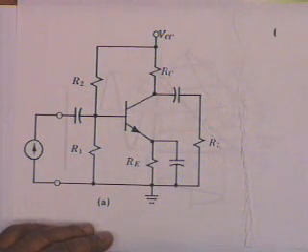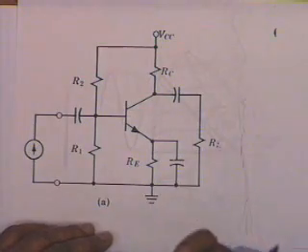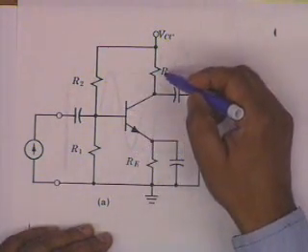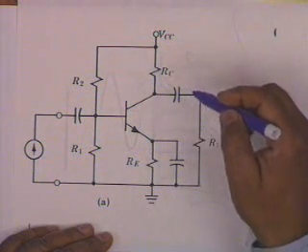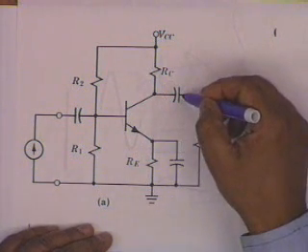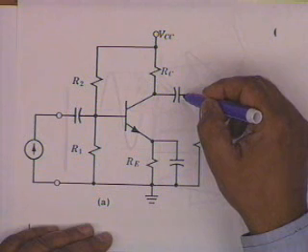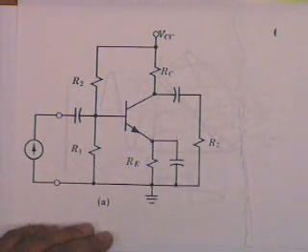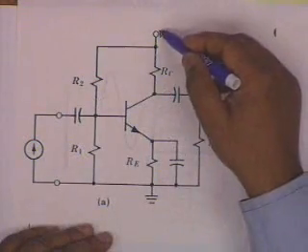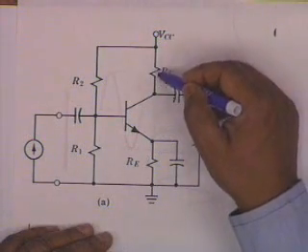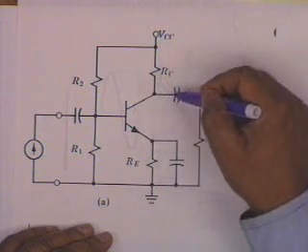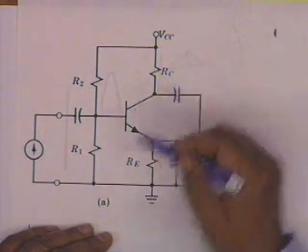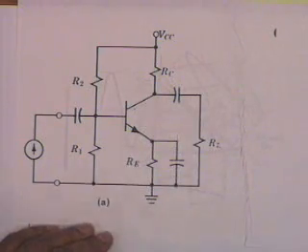RC, alright. How do you get this? Therefore, what you do is, for biasing you use an RC, but for load you connect the load through a capacitor, alright. This capacitor, if the capacitor was not there, then the biasing would have been affected, because VCC would not only pass a current through the transistor but also through RL, and therefore this is also called a blocking capacitor. It blocks DC.